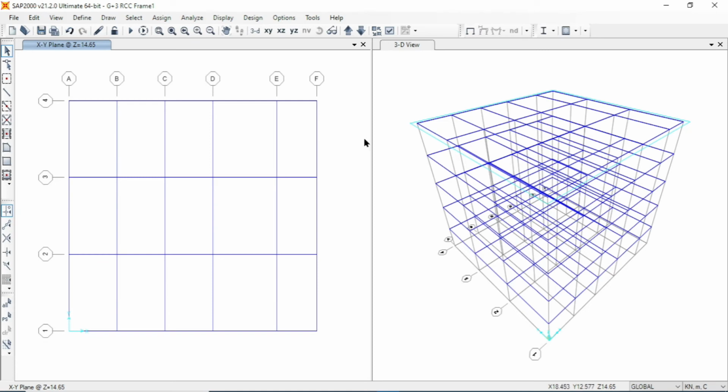Now I'm going to draw the column member here. To draw column member, I'm going to use extrude command. First I'm going to the plinth level beam. So now clicking this arrow, I'm going to plinth level. Now we are at plinth level. First I'm going to extrude the column from plinth level to foundation. Then I will extrude this column from plinth level to roof.